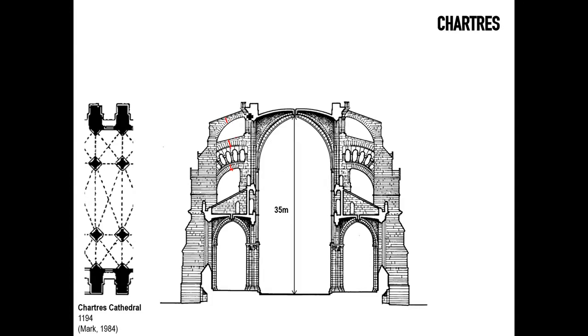And the top ones, some have argued that perhaps were somehow not as efficient as the rest, because you can see how the vaults here will discharge at this point mostly, but some of them up here will discharge lower than the actual buttress. So unless this buttress was picking up something from the roof, it's debatable perhaps. They're not necessarily absorbing the thrust itself, but they are still providing, according to Mark, a stabilizing effect to the entire structure.